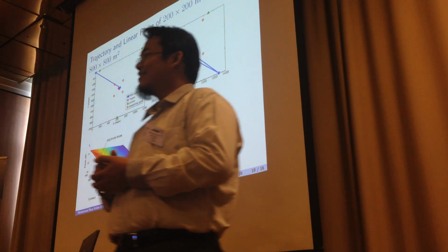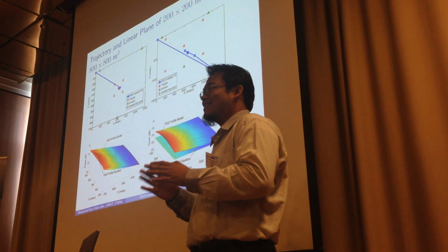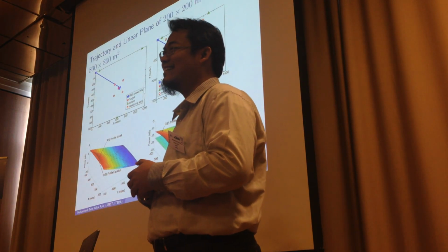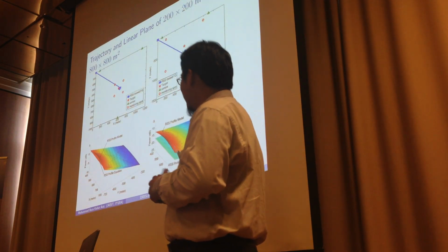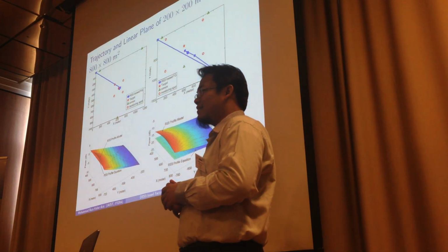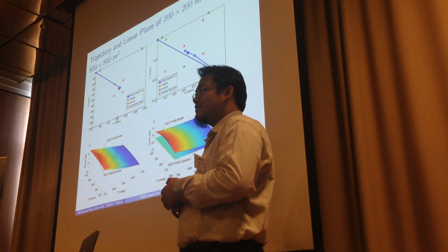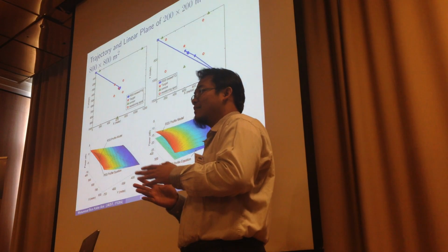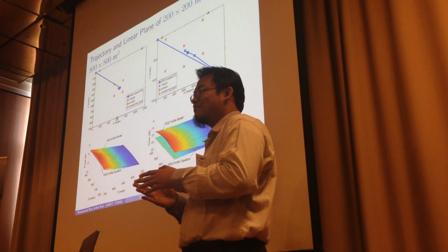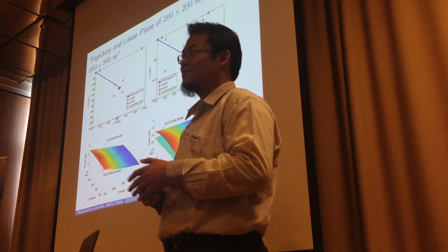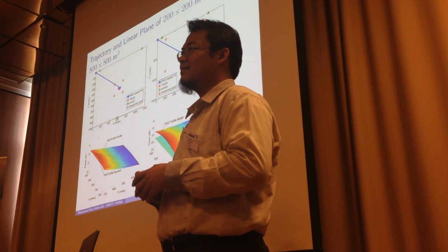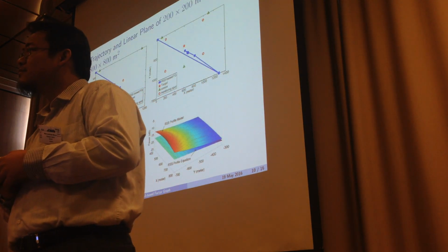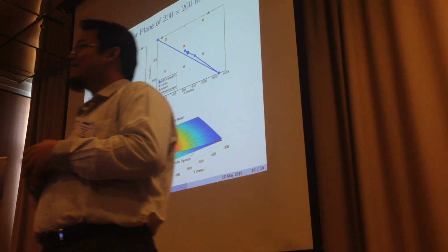Fading, flat. Actually, this is only a pure path loss exponent. So what does this assumption represent is the question. Actually, this represents something such as free space loss. We want to solve very simple models to show that the conventional technique cannot be used for that. So now you have the assumption that you have a direct relation between the RSS and the distance.